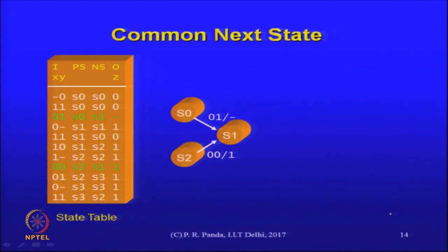Okay, let us go through some of the basic ideas of this particular strategy. This is a strategy that we are studying in more detail, primarily because there are some ideas there that are generic enough that help us formulate the problem, and help us understand the relationship between what happens at an early stage problem and its solution, such as this one, and its interconnection with a later step of logic minimization. Ideally one should be aware of what goes on there at the time that we make decisions here, but due to the sequential nature of the flow, we have to make certain assumptions. Rather than running logic optimization at this stage, we make certain assumptions and estimations about what will happen later.